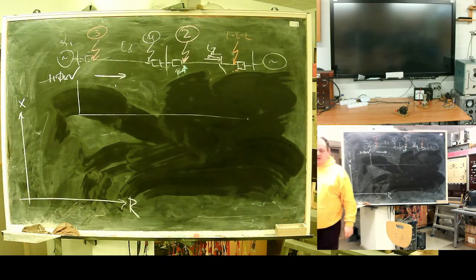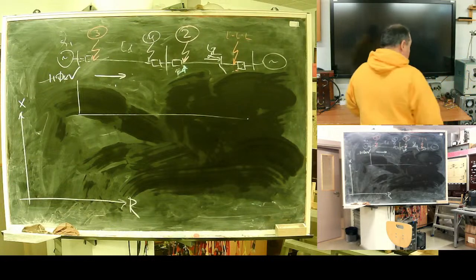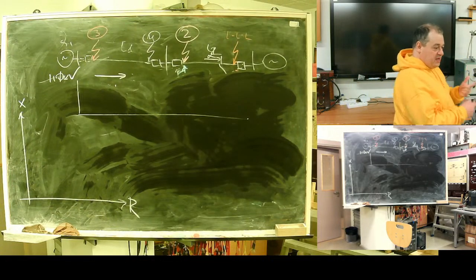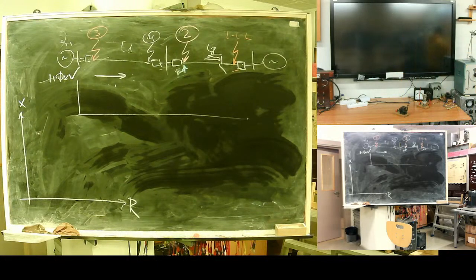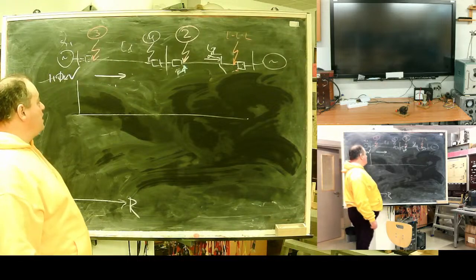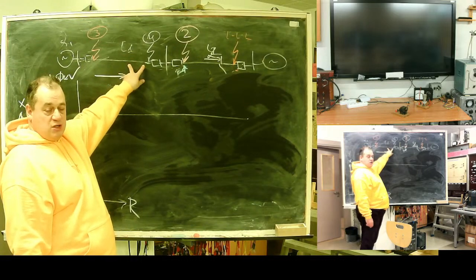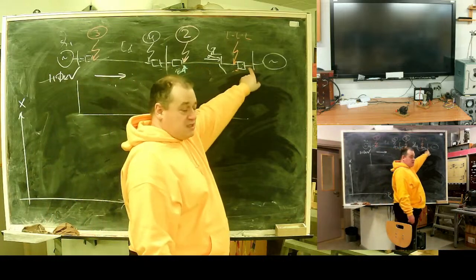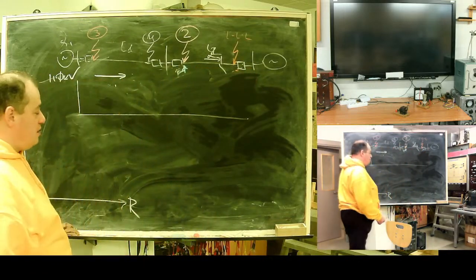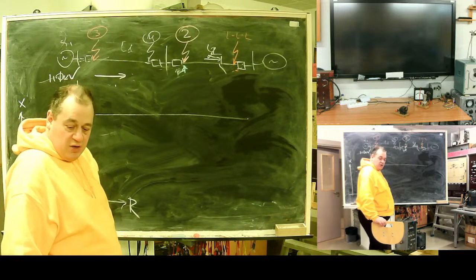How do we create selectivity zones or operational zones for overcurrent protection? First one, instant, operates instantly, but cannot protect the whole line because it should be separated by a safety margin from the instant zone of the second line. For overcurrent protection, the instant zone trips on 1.1 times max external current. Why is it 1.1? Because of a 10% safety margin for the error of current transformers.